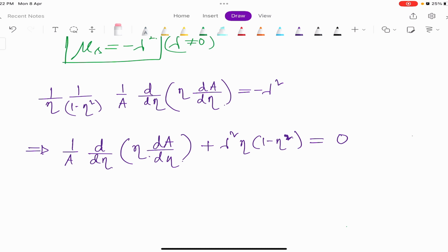There are mathematical methods to solve it, but now our next objective is to find the Nusselt number, the wall heat transfer, all those things. If I have to tell you all those things in a pure mathematical manner, I cannot proceed with this equation. But this does not mean that whatever we have done till now all goes in vain, because you have learned how to formulate the Graetz problem and what the Graetz problem is. Now this is the Graetz problem for a pipe, I mean for an isothermal pipe.